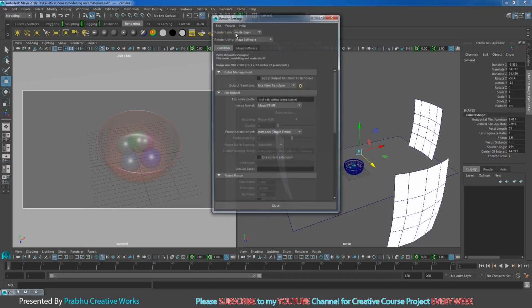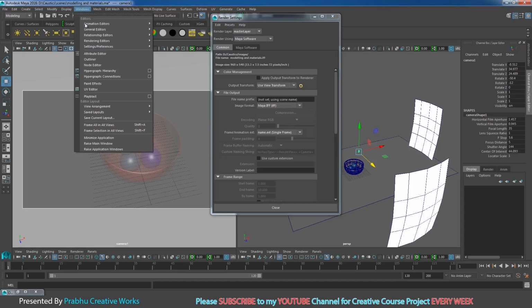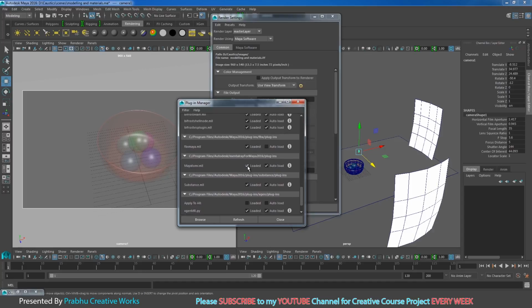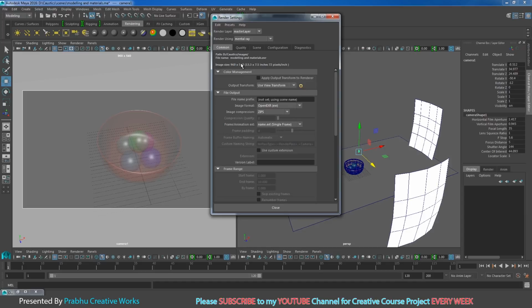Go to render settings. Here we have render using Maya software. You want to change this to mental ray. Sometimes it will not be available here. You want to enable it in settings and preferences. Go to window, settings and preferences, and choose plugin manager. Scroll down. Here you have the Maya to MR option. You want to check this one, load, and choose auto load. That means it will be available in your render settings. So I want to choose mental ray.